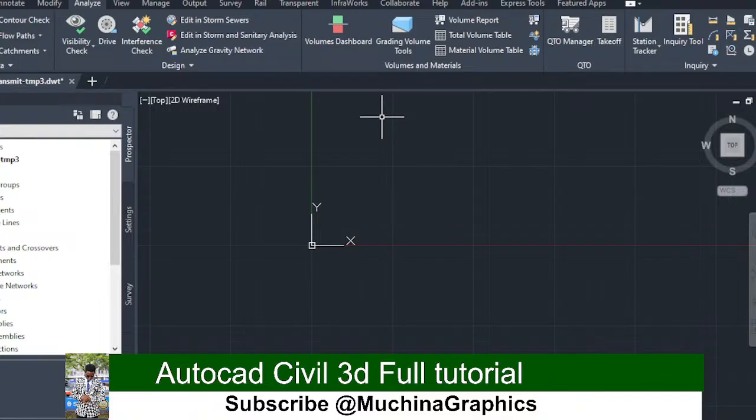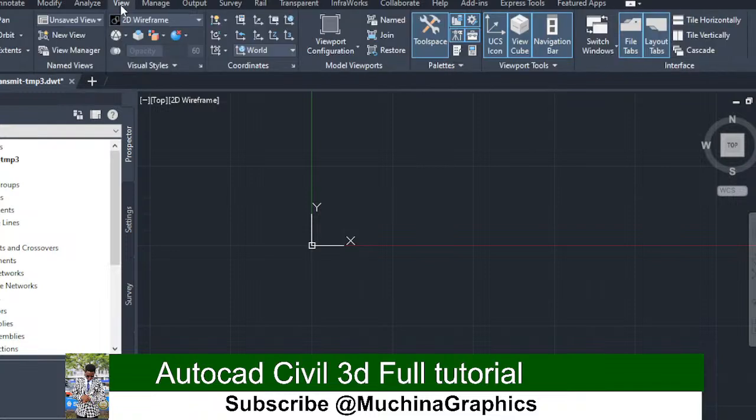So that then means a lot of transport cost, and you can avoid that at design level, ensuring that if the material is checked at site and it has met the standards, then you don't have a lot of cuts and rest of fill. So you balance the two so that the material that is being cut here is filled there next, and that way you don't incur a lot of cost.